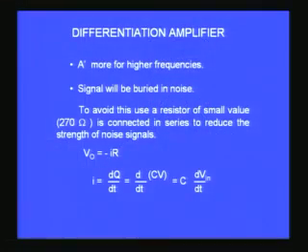So therefore what is going to happen if I have a specific signal, maybe a square wave or something, even a sine wave, there will always be some noise voltages coming in at the input. Along with the signal there will be some noise added to that due to extraneous reasons, and these noise can have different frequencies. We have no control over them, and therefore the spectrum of the noise can involve very high frequencies as well as low frequencies.